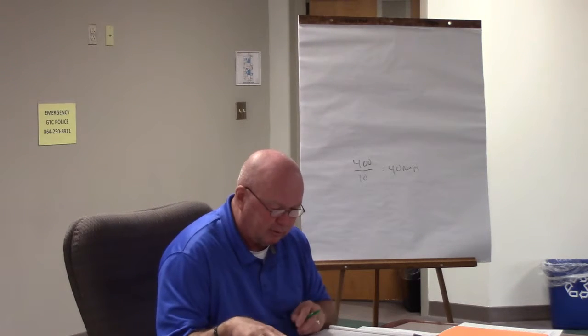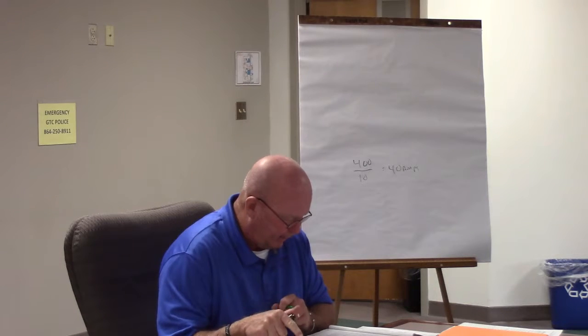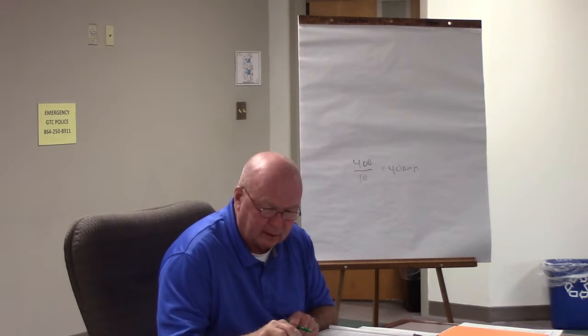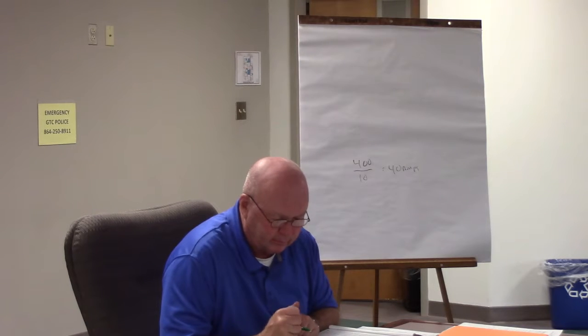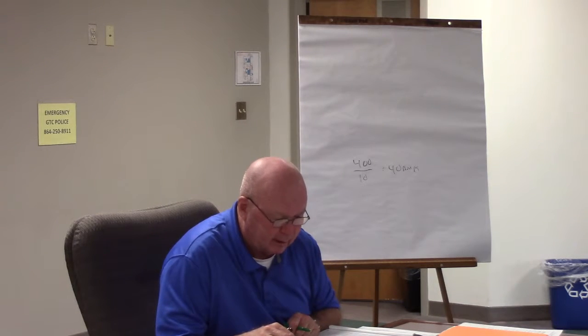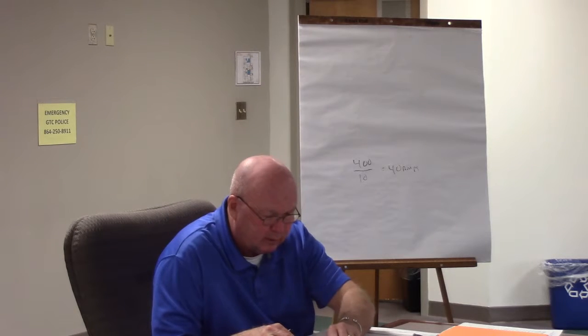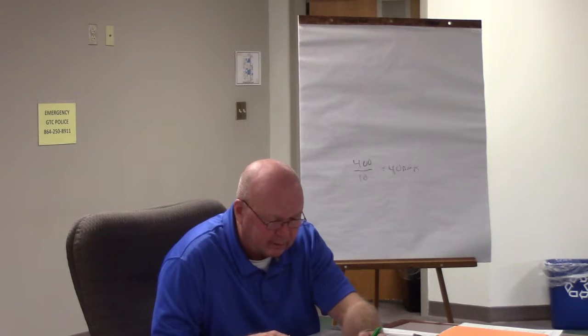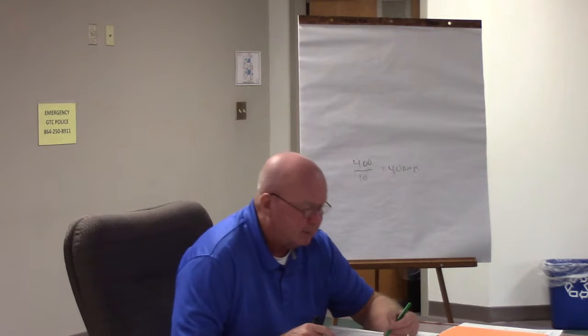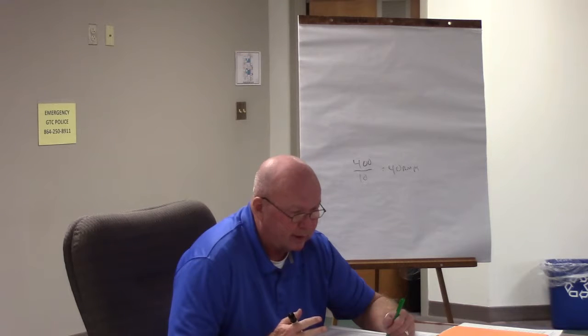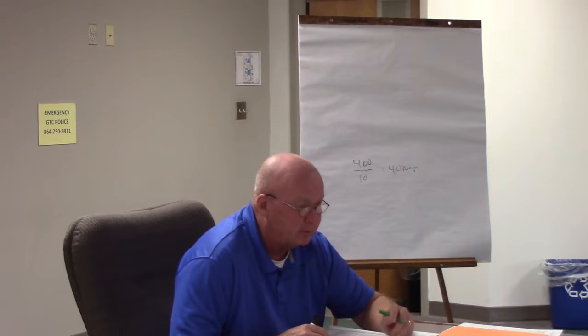So we go to 240.21, B2. Let's see, 240.21, B2. Found that on mine at the top of the page. Not over 25 foot, and it gives us 3 bullet points, but let's read the bullet points from the book, okay? You may read the first bullet point. The total length of the tap conductors must not exceed 25 foot. So, total length, tap conductors, 25 feet.